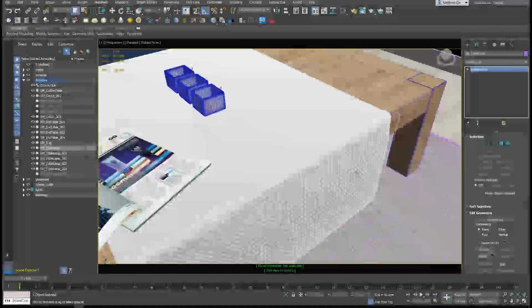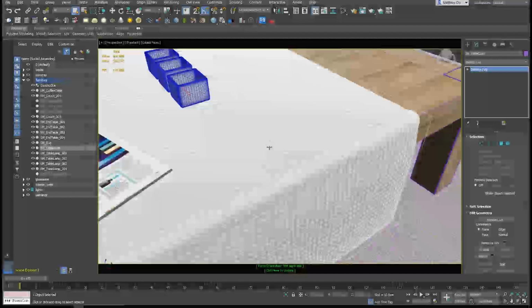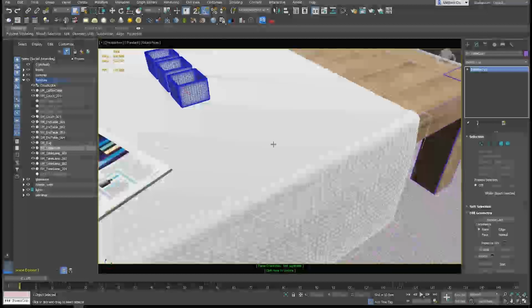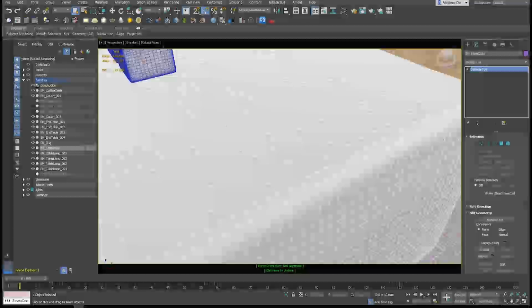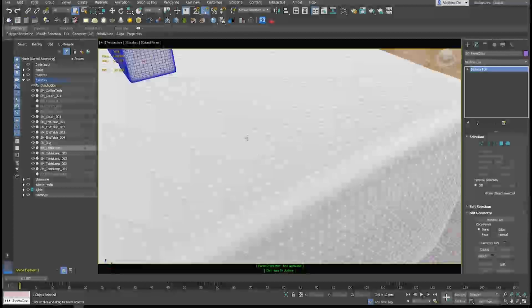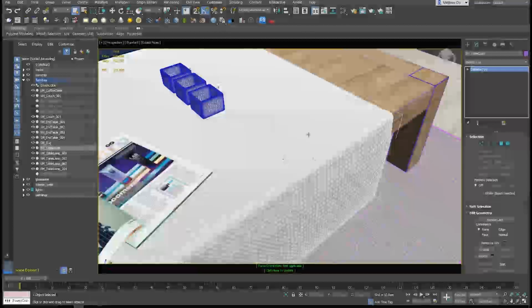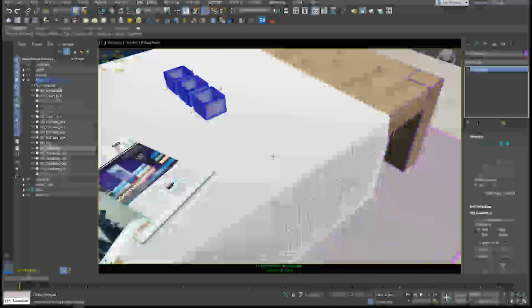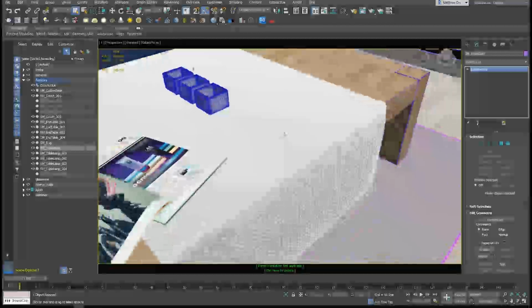Now, you can use quads or triangles with Unreal, and you probably won't see any issues. The only real reason to use quads over triangles is that, by doing so, if you need to subdivide a mesh or reduce its complexity for an LOD, it's going to do so in a much cleaner fashion generally. It's a lot easier to subdivide or reduce the quality of a mesh that's made up of quads. Because if you're going to increase the complexity of the mesh, it's very easy to subdivide it into a version that is just as clean as the original version of the mesh. As well as LODs, when you're reducing the complexity, quad-based meshes will reduce a lot cleaner than meshes that are composed purely of triangle soup.